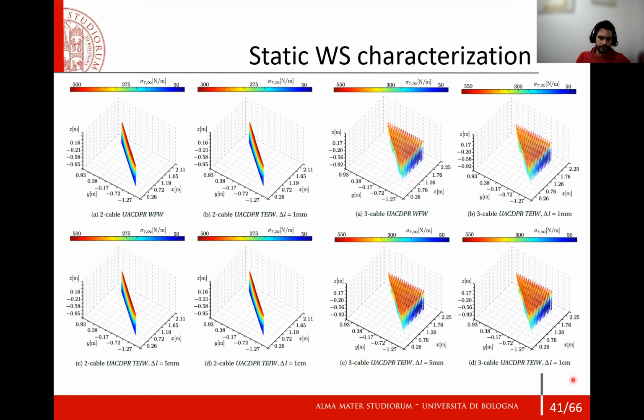We may see that the tension varies very much when cables are more horizontal and the end effector is in the upper part of the workspace, which is colored red. And we also can see that these two architectures, 2-cable and 3-cable robots, are not very influenced from a range feasibility point of view by cable actuation errors, since the workspace size does not change.